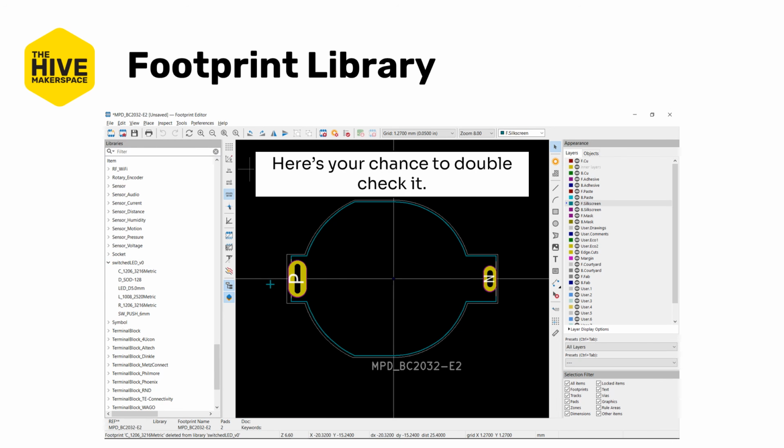Notice how much nicer it looks. Also notice the 3 outlines. They also intelligently put the positive indicator outside the part outline, meaning the user can actually see it after assembly. This would be a good opportunity, if you remember our failure in the design to match pin numbers and pad numbers together with the battery holder, to edit this to make it 1 and 2 instead of P and N. Once you're done with all of that, you can then go ahead and save it.